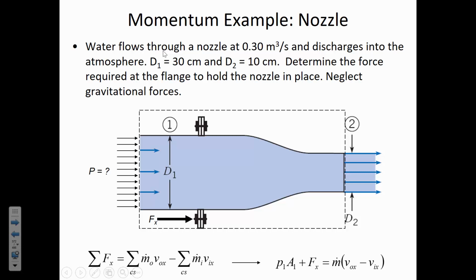There's the flow that's changing velocity. That's going to be one effect, but the other effect is this pressure that's acting from the left towards the right on our control surface. I know it's strange to think of that, since this is an imaginary control surface, yet we're pretending as though it's a force that's actually applying on it.